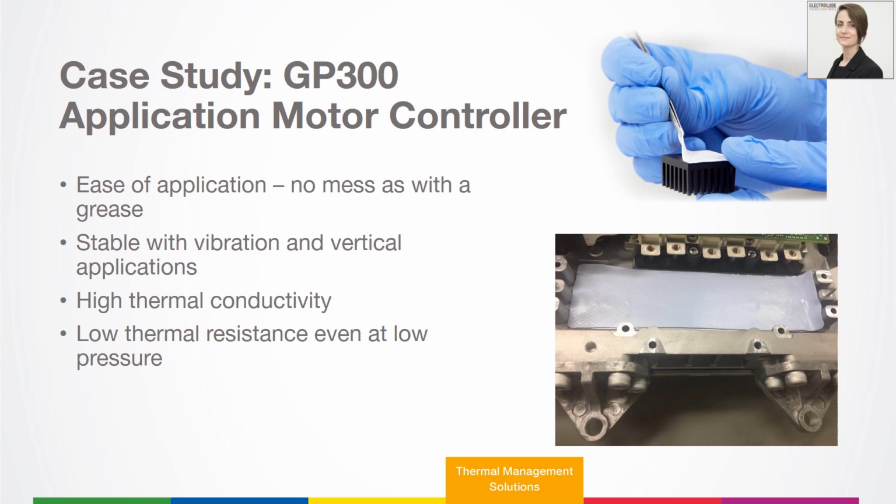Due to its high surface area, where they needed the thermal interface material to be applied to, and the temperatures involved, they needed to ensure that something curable or cured was used. In this case, they felt that a thermal paste would move too much due to the large surface area. A gap pad was the ideal application because it didn't require any specialist equipment to apply it, and it was reworkable as well, so it's much easier than something that cures in place.